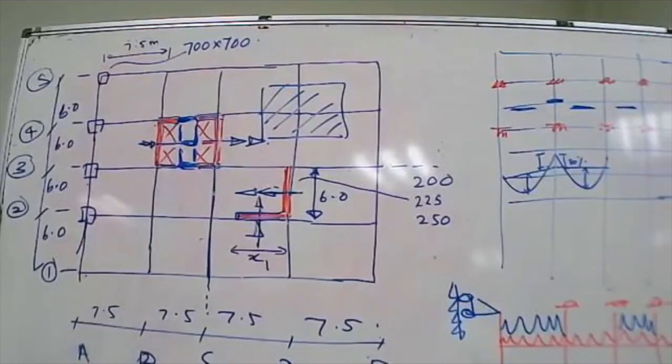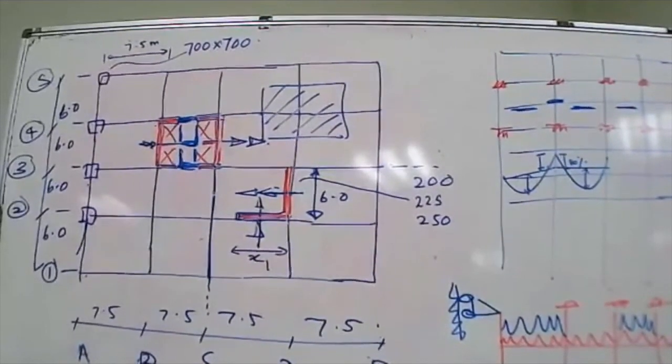So basically, why we don't want to continue too much reinforcement across the column is that we have congestion of reinforcement, right? So if you think the point of contraflexure is changing, you can adjust the reinforcement cutoff points. In such situations, rather than trying to do a lot of accurate calculations, I would rather use a simple rule.